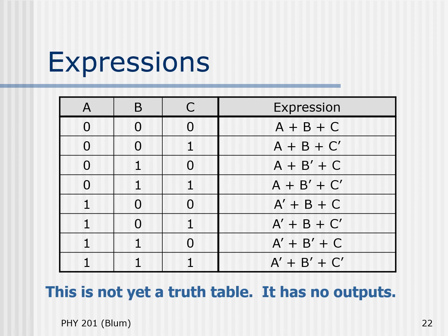Shown here are the expressions for each row. Remember that we are going to write an expression when the output is a 0, and we want an expression which is 0 for that row and 1 for all others. So our first row is A or B or C. That would give me a 0 if A is 0 and B is 0 and C is 0, and it would give me a 1 for all other possible inputs.